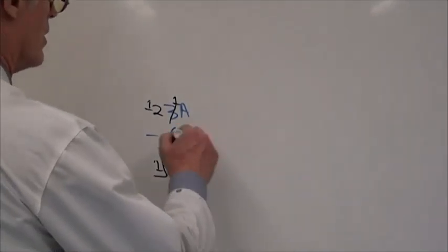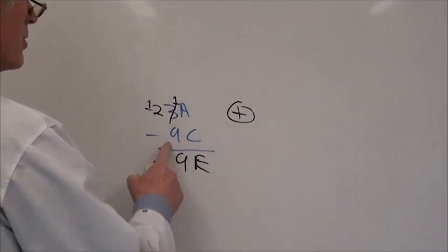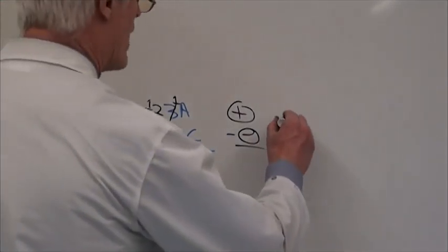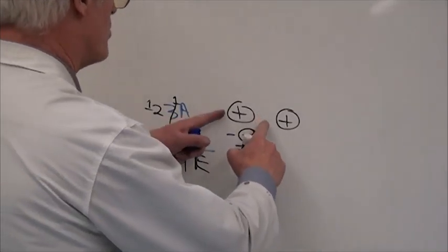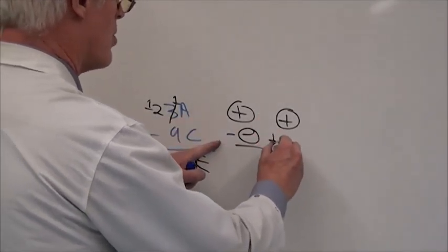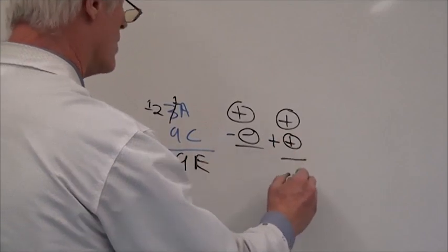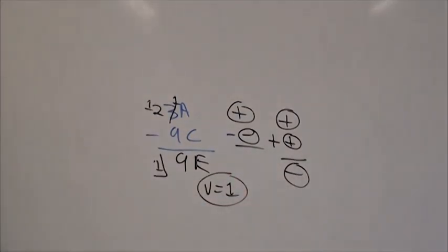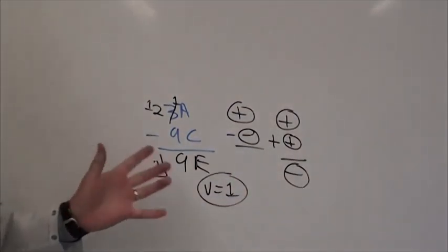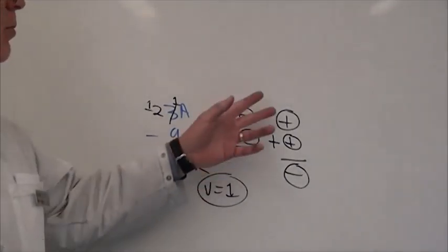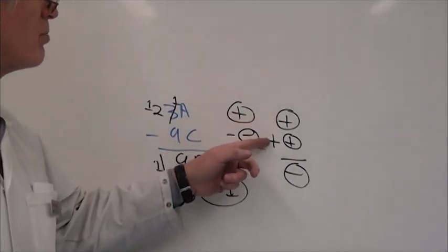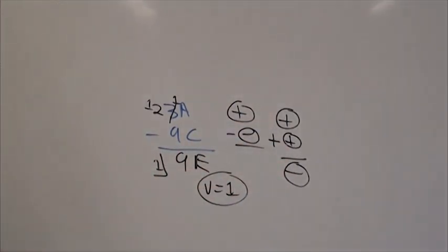But what we want to do is figure out, is the overflow set by this? The signed overflow. Well, if you look at 3a, that's a positive, and you're subtracting a negative. But as we just saw, if you want to convert a subtraction into an addition, you have to add the opposite sign. So if this is a positive subtract a negative, that's the same thing as a positive plus a positive. And in this case, we've got a negative, and therefore V is 1 for this guy. So when you're doing subtractions, you have to rethink. You don't have to do the calculation, but you have to think, what would this be as a 2's complement addition? If this is the same as a positive plus a positive and got a negative, you got V equals 1.